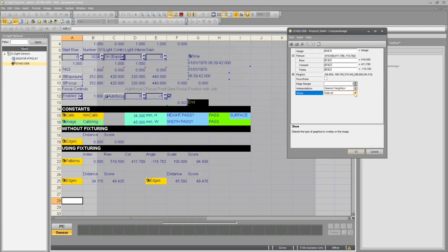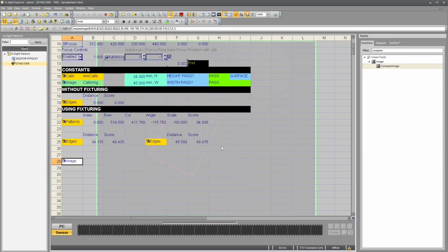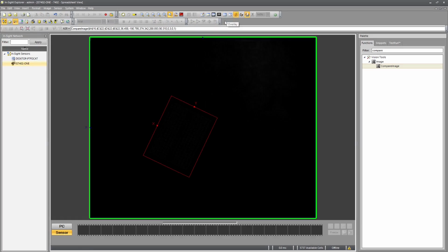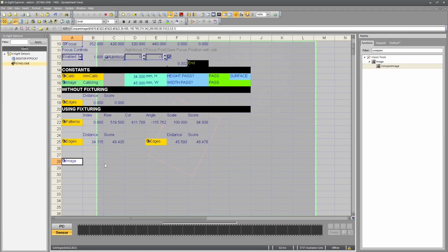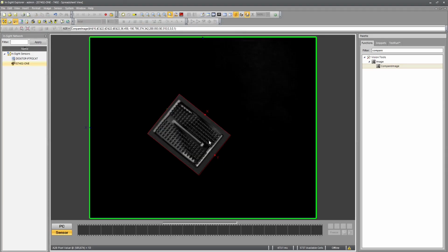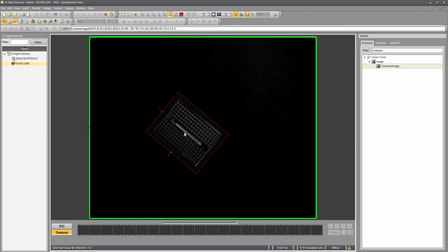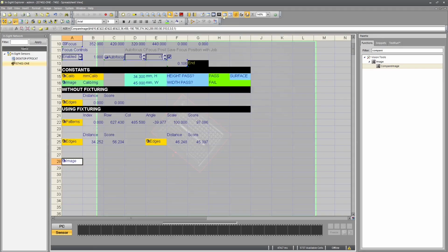These options are not very important, and we'll do result graphics. So if I hit OK here, you'll notice that now, because my image that I've triggered is identical to my trained image, there's no difference whatsoever. But if I were to, say, rotate this and maybe cast a shadow over it and trigger a new image, you can see that because there's a change in the lighting condition, this now appears to indicate that there's a difference in the parts that are there. If I take another picture, it darkens significantly, which means it's pretty much the same.